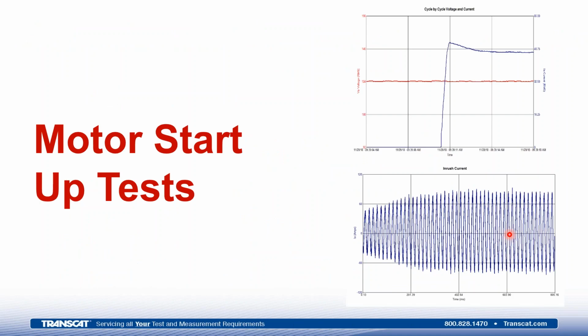Motor startup. You're going to want a good analyzer that can record all parameters on a cycle-by-cycle basis. So when the motor starts up, you can capture over 600 cycles of inrush current. We have our cycle-by-cycle voltage and current waveform chart and our inrush current waveform chart.